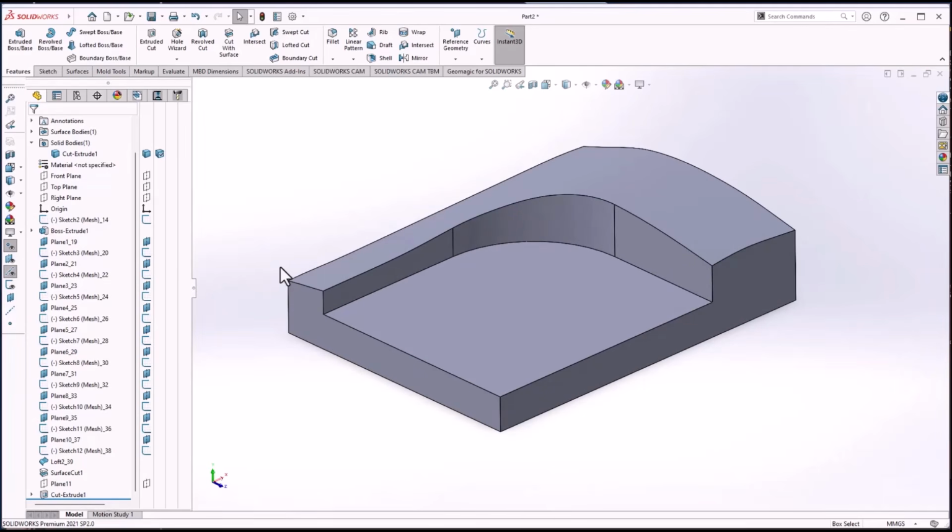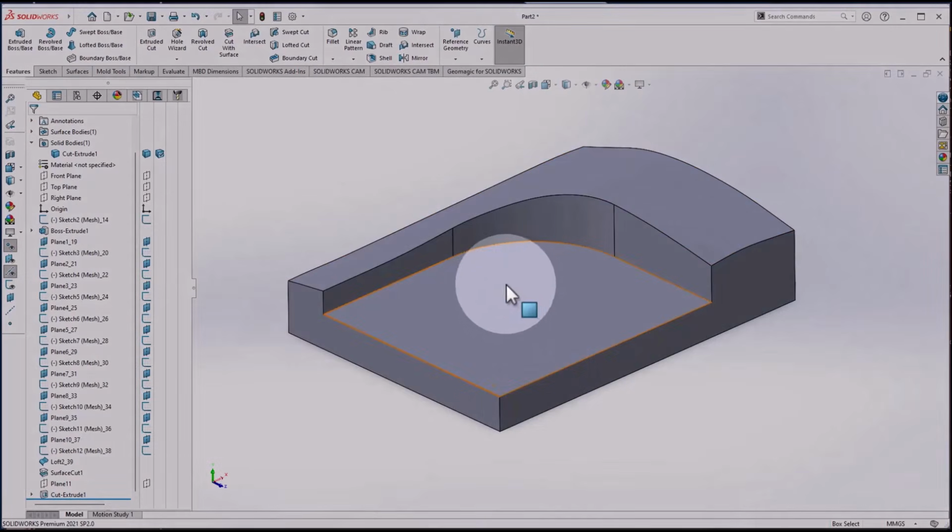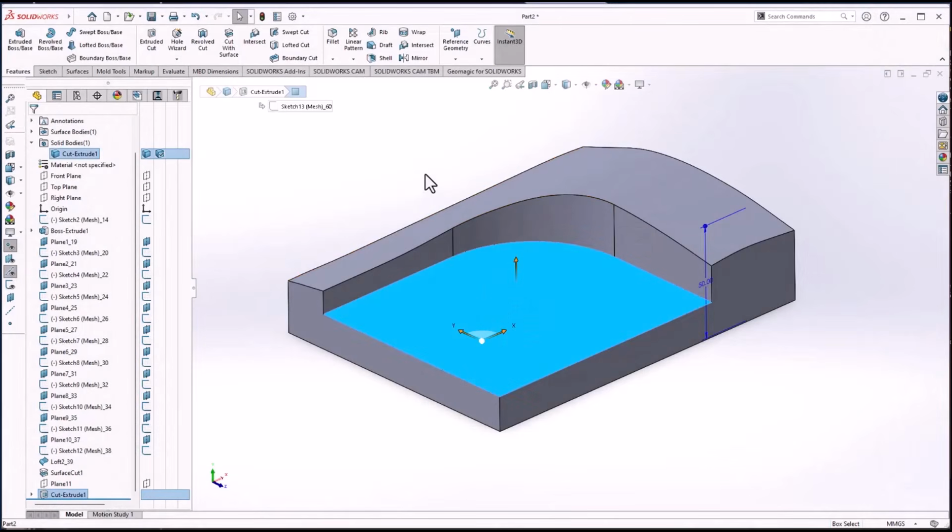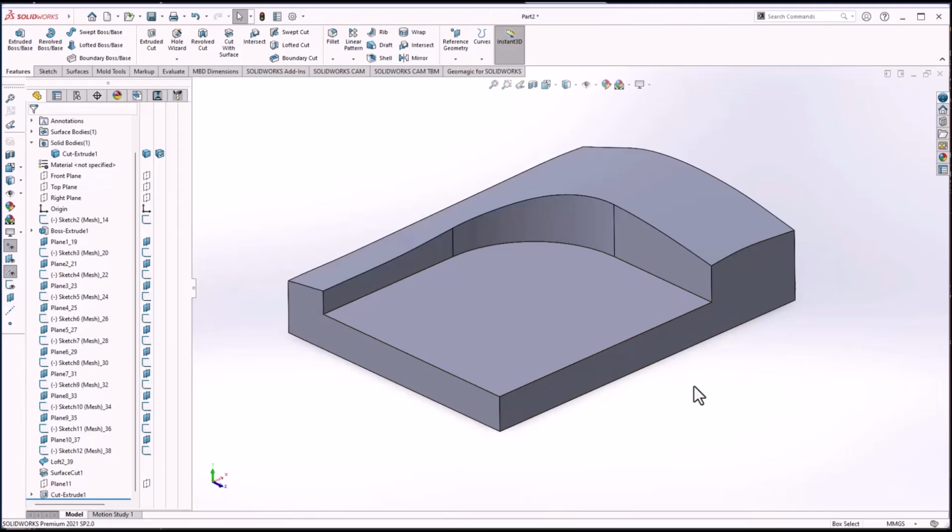I send it as I went, and if I have dual screens, I just send the model, and I keep going. And when I'm done with this, I can save the SolidWorks file, load the SolidWorks file back in to DesignX and do a 3D comparison if I need to compare to the CAD. So this is kind of like a hybrid live transfer workflow.